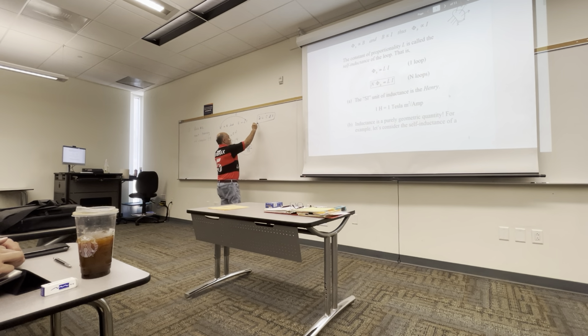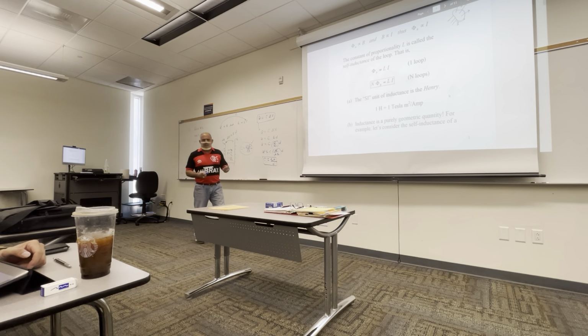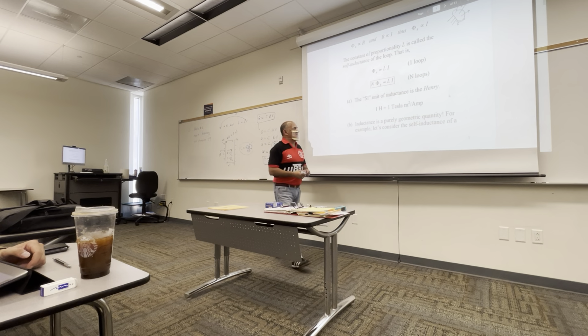you can just start with this if you like. So Q equals C delta V. And so this is Q equals C, and delta V is E D. But E is sigma over epsilon naught, times D. But sigma is the charge per unit area. You have epsilon naught times D, so this cancels that. And C equals epsilon naught A over D. Just this. And you can do something similar to this to calculate